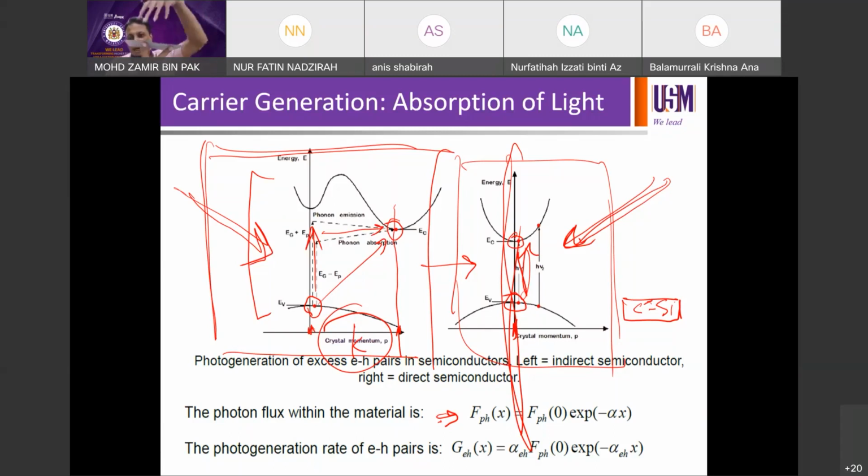The light, the photons, come from the top and penetrate into this silicon. The silicon thickness is roughly 180 micron, about twice the thickness of your hair. If you pull out one hair, you put two strands together, and their thickness is about the thickness of this wafer.